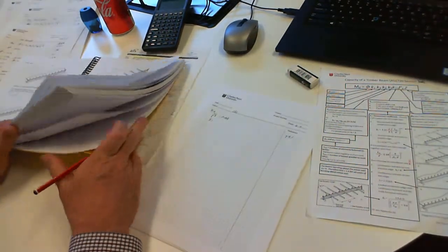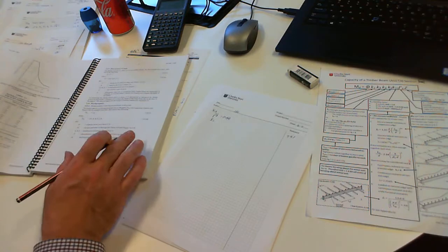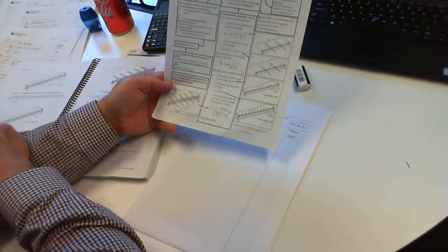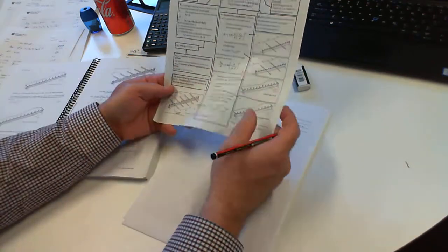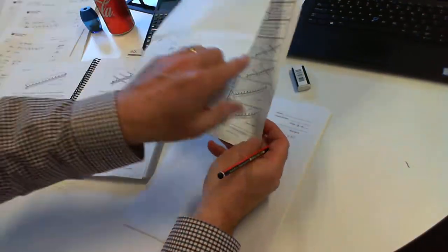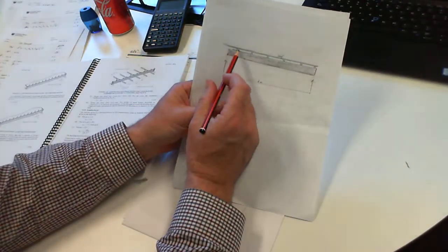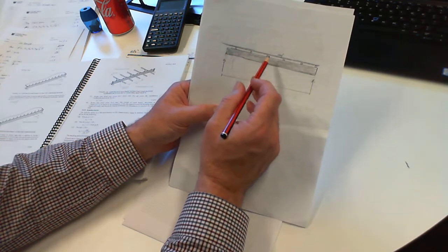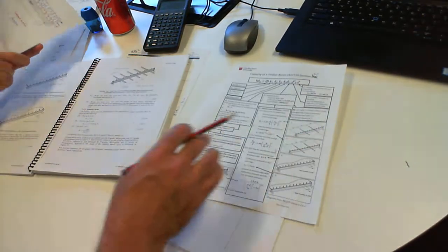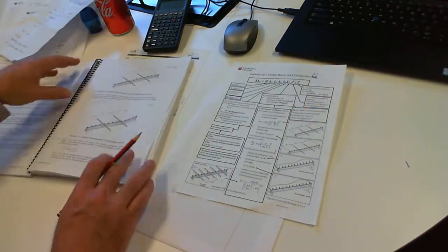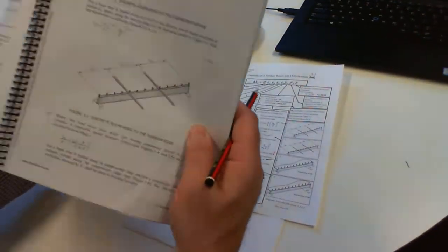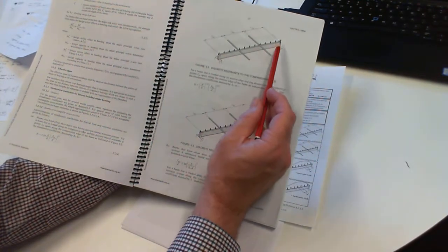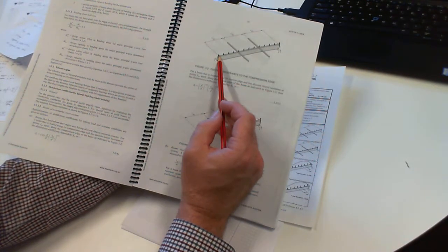Our slenderness ratio is all about the restraints this has. Now you recall that I said this is restrained by these battens at 900 millimeters. So those are 900 mil apart. These are top restraints to this beam, which is most like that picture there. We've got the load applied to the top of the beam from the roof.